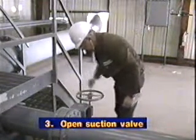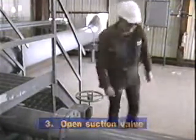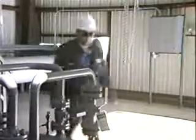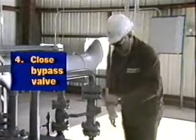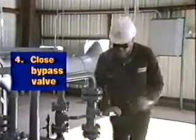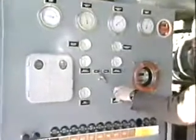Doing this allows the same gas to be continuously cycled through all the stages without compressing it up to sales pressure. Once you close the bypass valve, which is the next step, the gas will be compressed up to discharge pressure and leave the system through the discharge line.